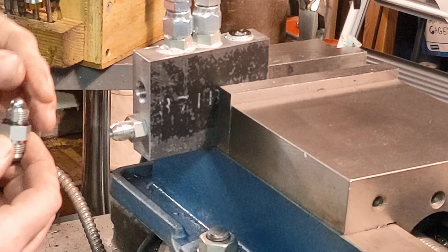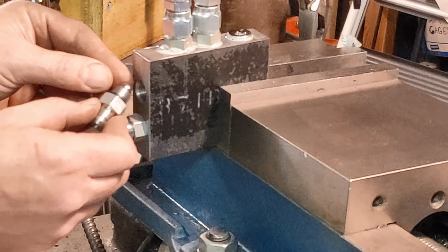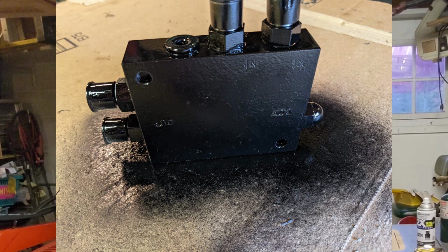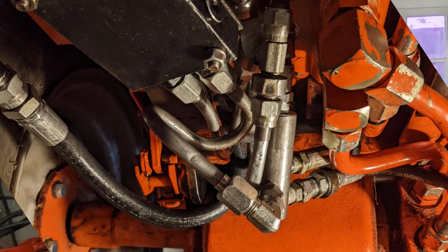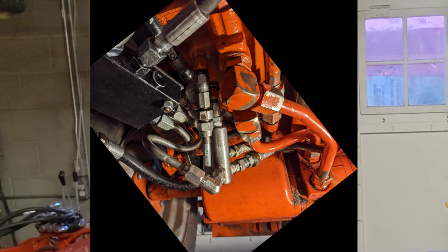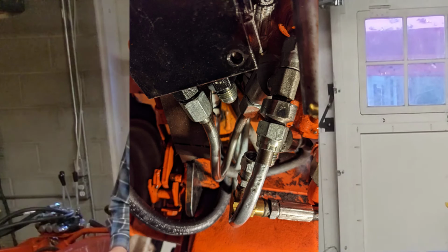After I assembled the new component, I tested it with 100 psi air pressure. I ended up having to lap the seat where the pressure relief ball seals. After lapping that seat, I had satisfactory seals against air pressure, and if it'll work for air, it'll be fine for heavy oil. Installing the new component into the tractor was a struggle. I had to add these very tightly bent and twisted 3/8 steel hardlines into an already cramped space. After a few more hours of struggle and frustration, it looked like everything was installed and everything was tight.